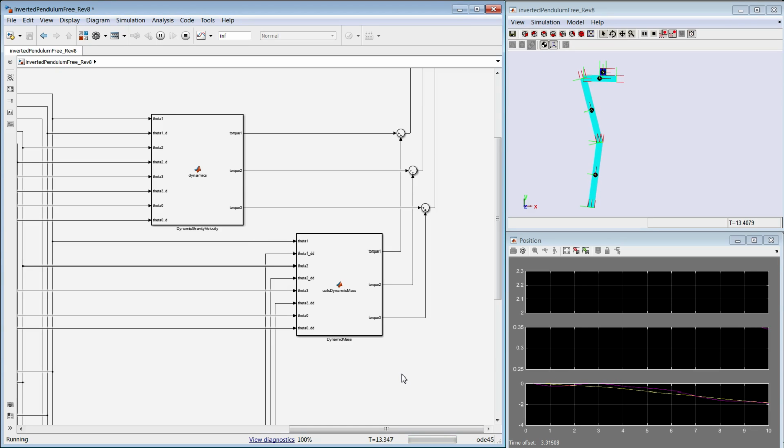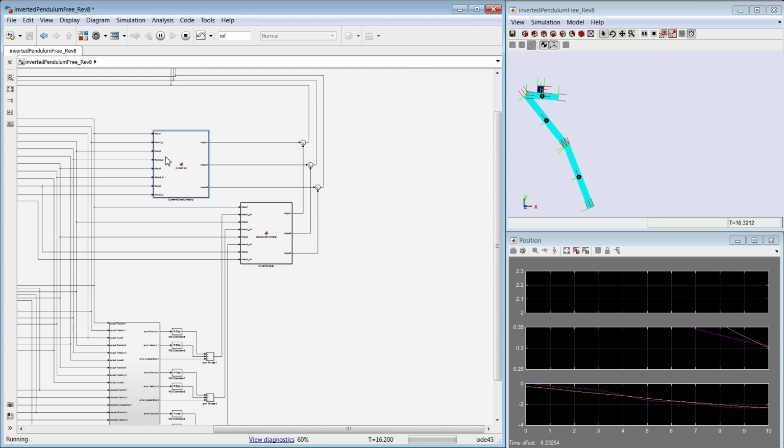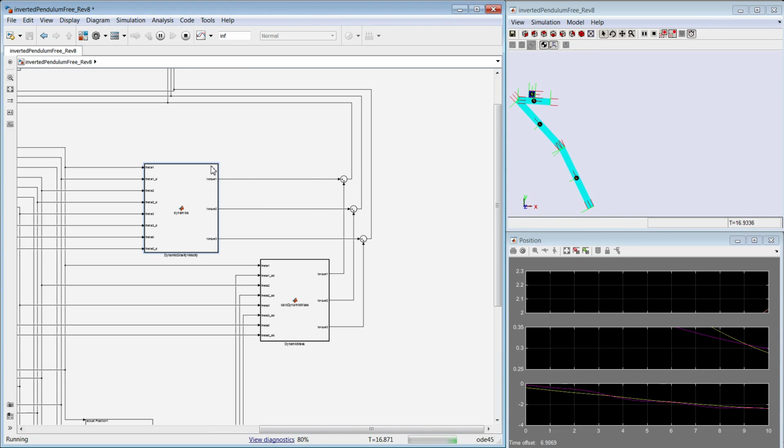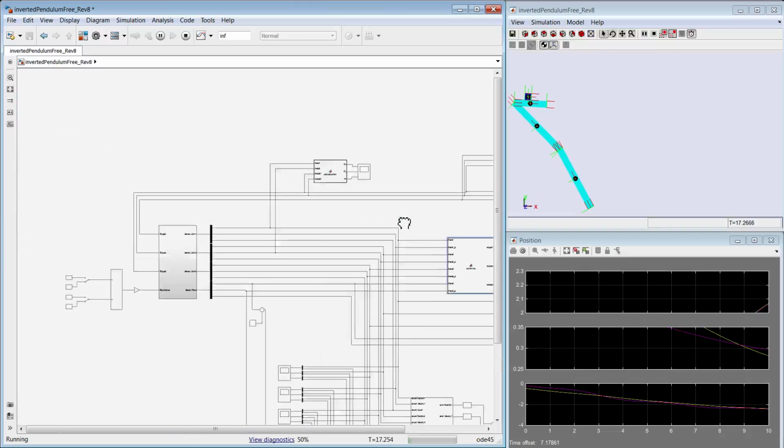There are two manipulated dynamic blocks because this one accounts for the mass effects, and the top left accounts for centripetal, Coriolis, and gravitational forces that will be acting on the system. The two torques are then summated and sent back to the simulation model.